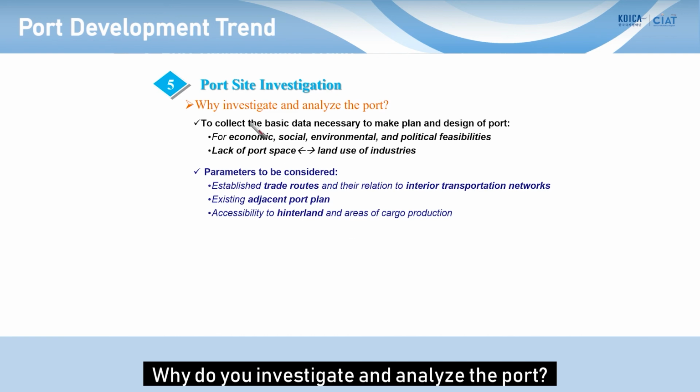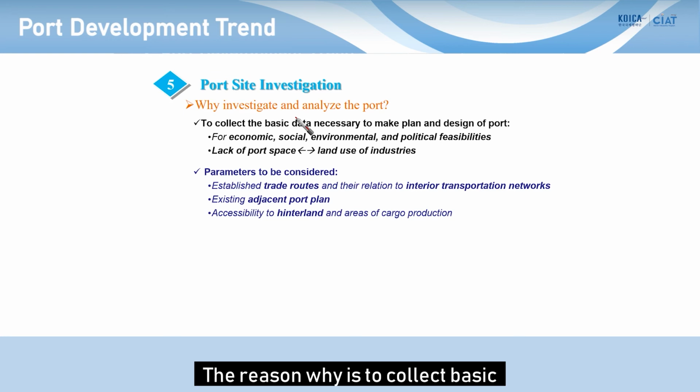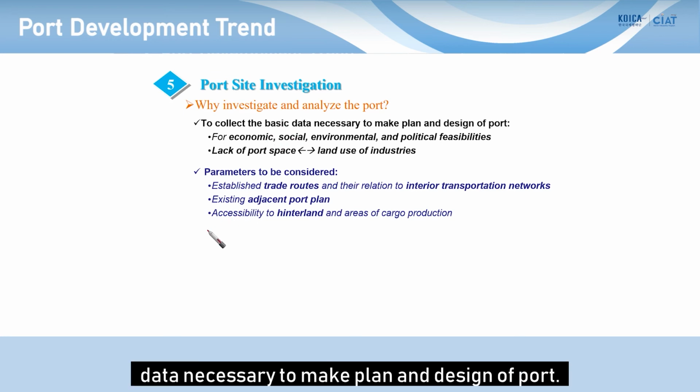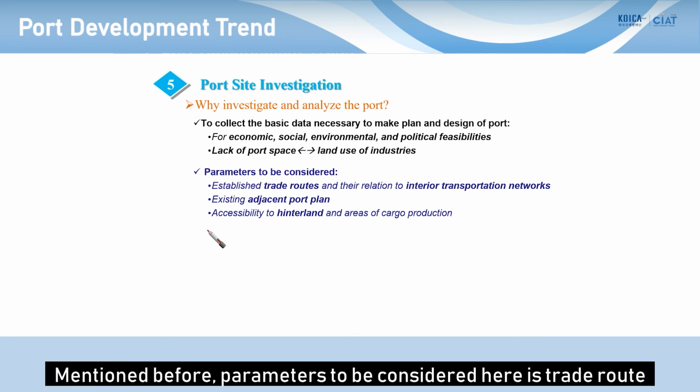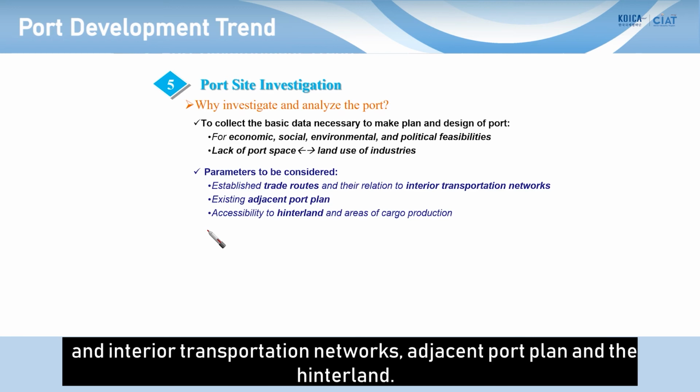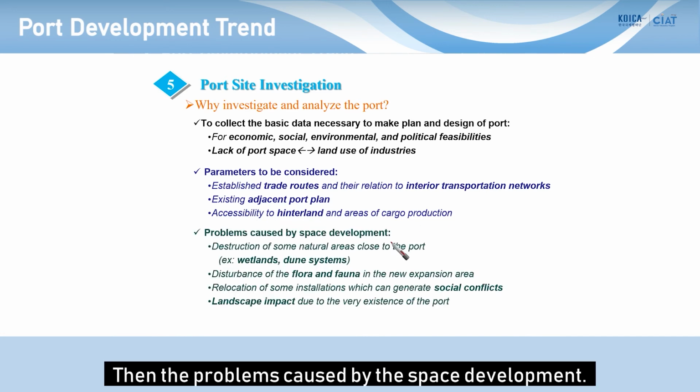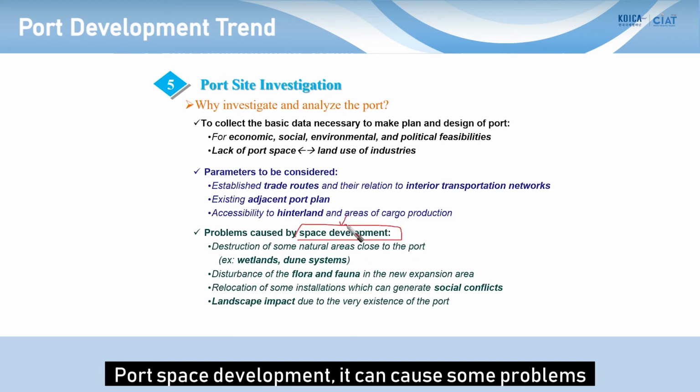Why do you investigate and analyze the port? The reason is to collect the basic data necessary to make a plan and design a port. I mentioned it before. Parameters to be considered here are trade routes, interior transportation network, the design of the port plan, and the hinterland. Then the problems caused by port space development: it causes some problems.